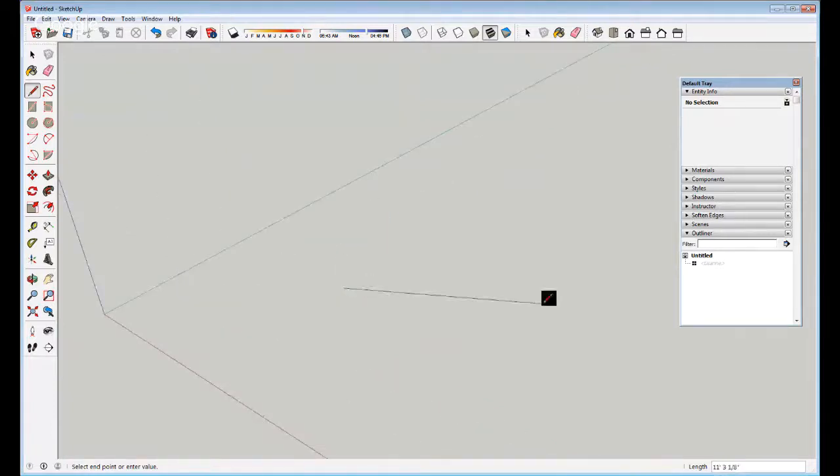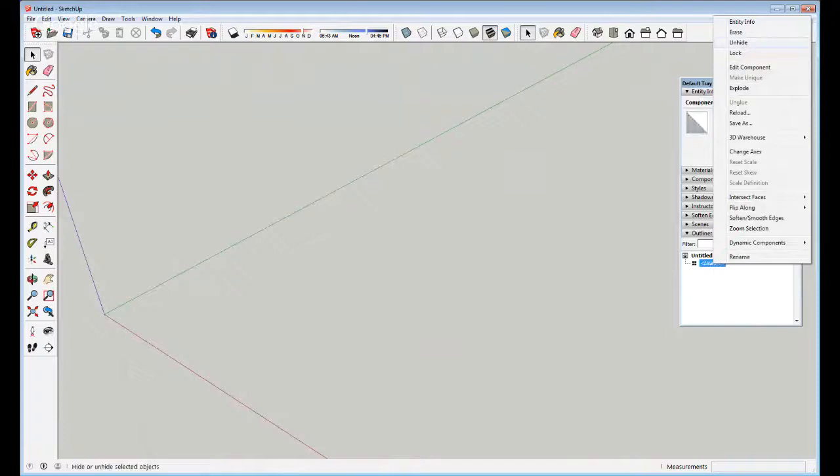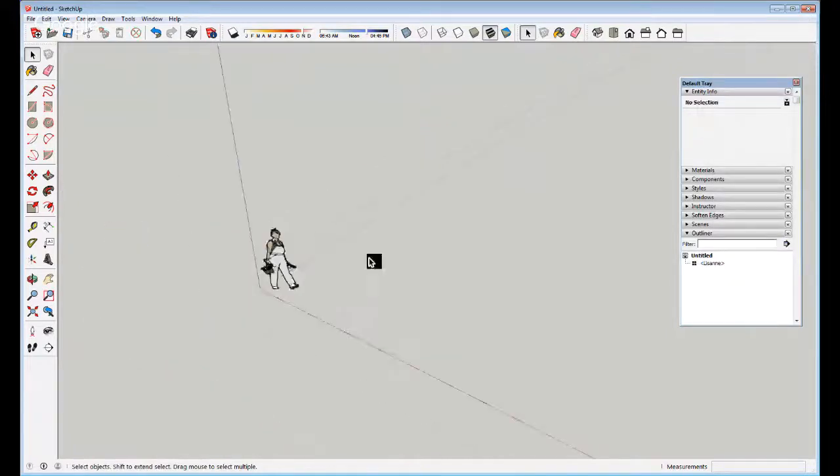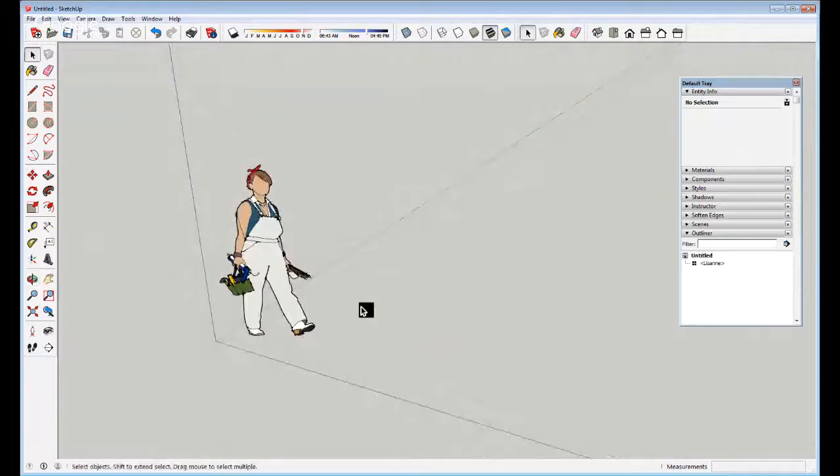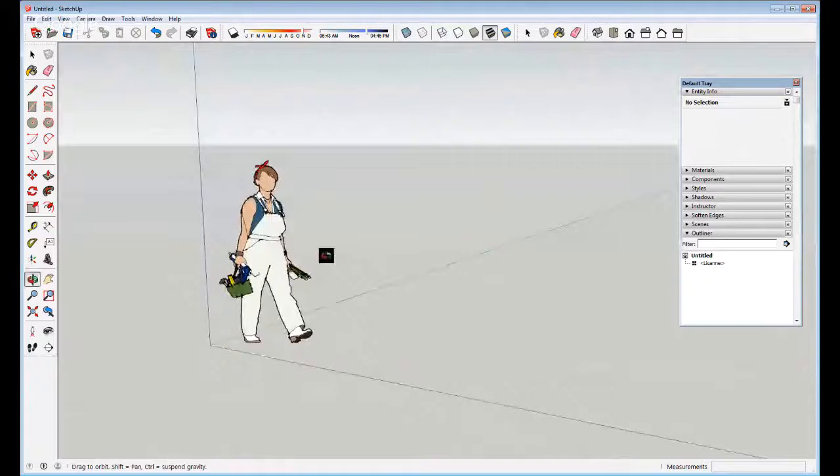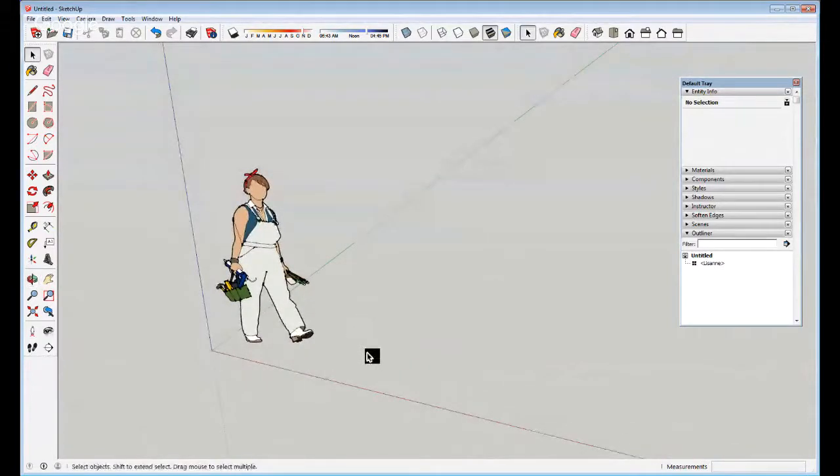to create, because you know what, let's turn this person back on. So let's say Anne wants to have a table. Maybe because she wants to put all of her tools and things down, and she wants to rest. So let's say we want to create a 5 by 5 by 5 cube so that she can just set everything down. As soon as you have this line started, I can literally type in 5 and then just an apostrophe for feet, and then press enter.